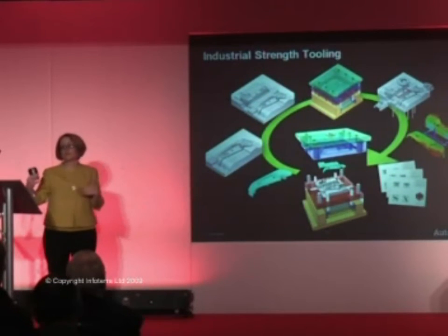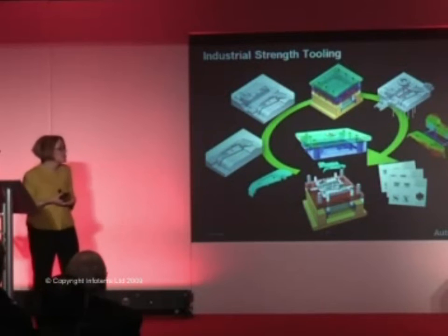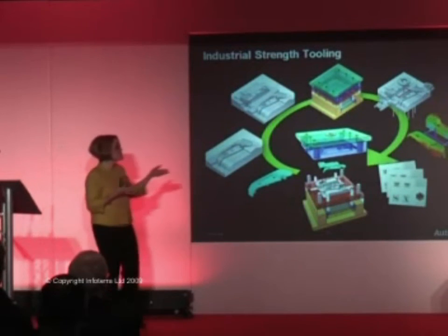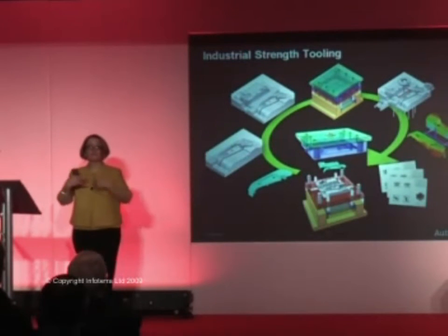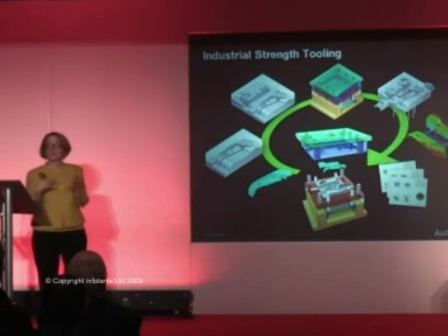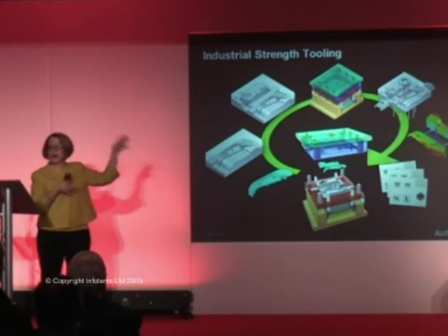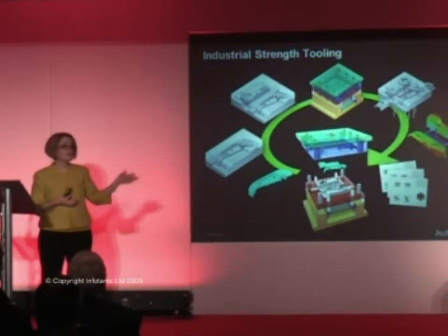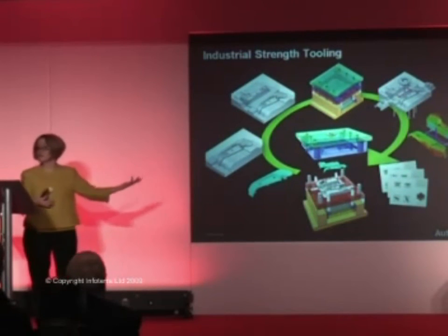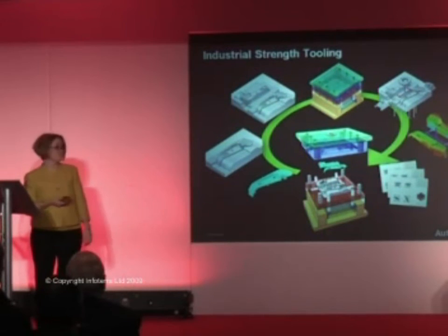And that's historically something that takes a long time, and a lot of people do it in AutoCAD and don't have it connected to their 3D data. The other thing we've done is we've added some of the mold flow simulation into this product. So this is where we're starting to cross-pollinate some of the acquired technology into Inventor, so that you can do some quick studies to see how the melted plastic is going to flow inside of the mold. It's very easy to set up because we know it's a mold, we know what you're trying to do, so it's not hard for the user to get some very quick results.